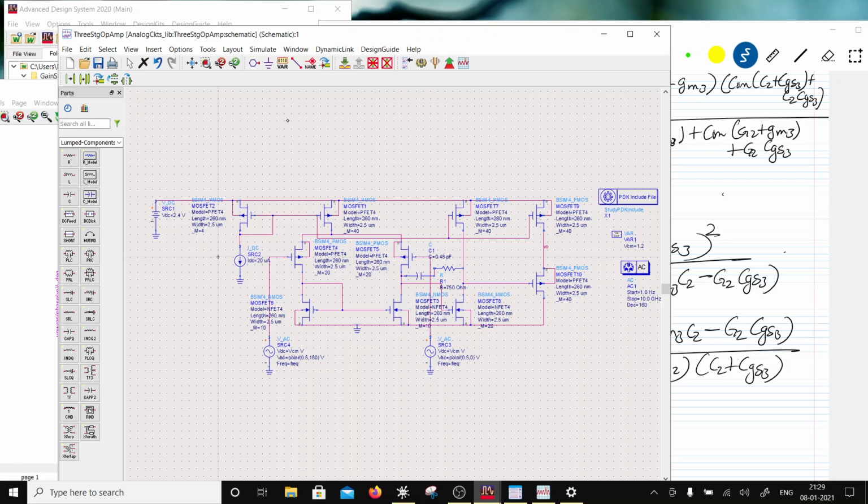For example, if there is a low voltage requirement, then I would make a cascode, folded cascode op amp, or I can make an OTA, and then I would also discuss, if there is a differential in, differential out, then I will discuss common mode feedback circuits and all that also in the next sessions as the need arises, right?